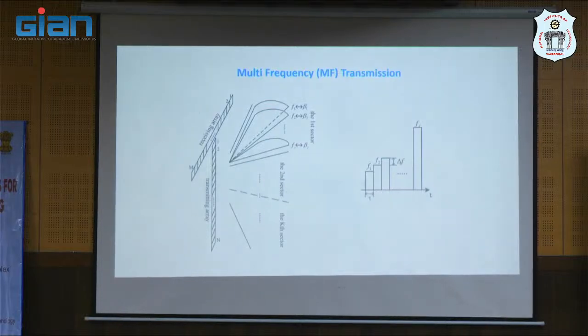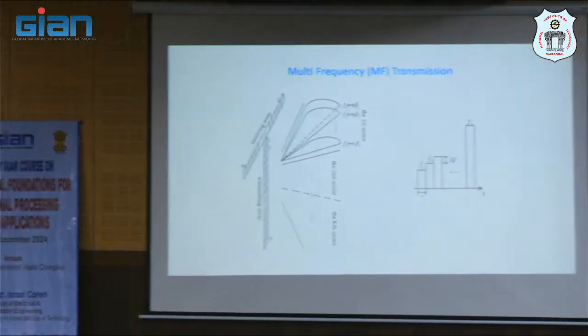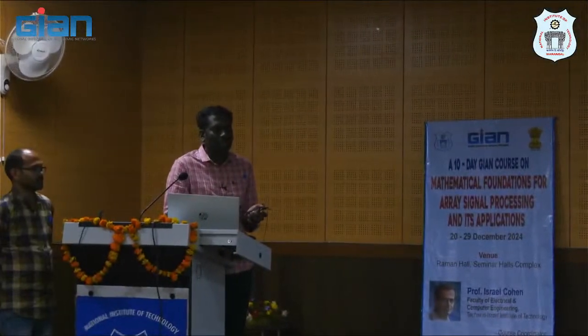It is related to frequency, sir. If frequency is lower, the signal will penetrate. Generally if frequency is between 5 kilohertz and 15 kilohertz, we will get penetration. But for high resolution, we have to go for 100 kilohertz or 400 or 500 kilohertz. So there is something we have to compromise. If we need penetration, we have to go for low frequency. If we need high resolution, we have to go for high frequency. Otherwise, some sub-array arrangement has to be arrived at. Thank you.